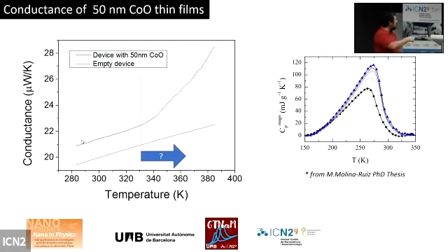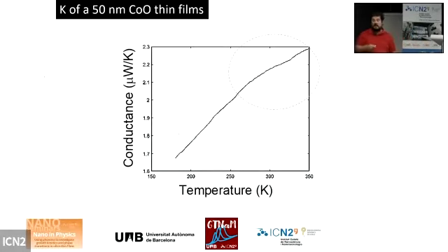But if we pay attention to a sample without going so high in temperature, at low temperatures around the phase transition temperature, we were able, with less resolution, of course, than nanocalorimetry, to also follow the phase transition, the Néel transition, through the thermal conductance. In that case, I would say the mean free path of phonons in that kind of material will be more or less constant because of the grain size, and this is essentially linked with the change in heat capacity that we can monitor.